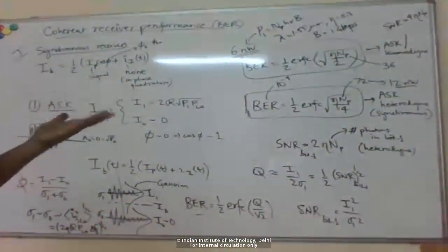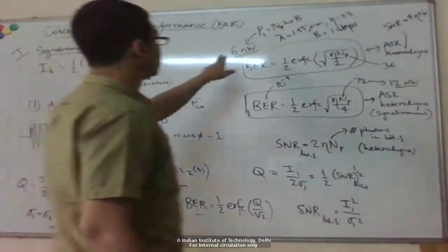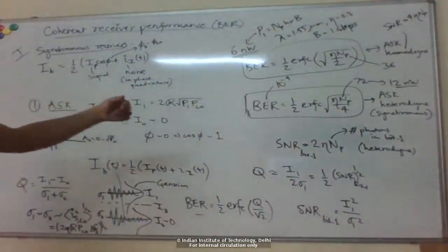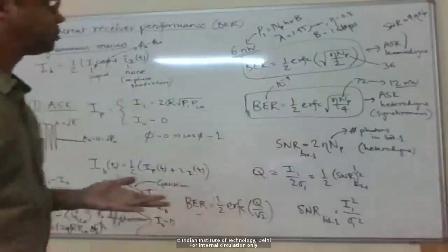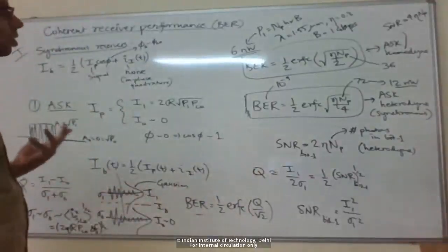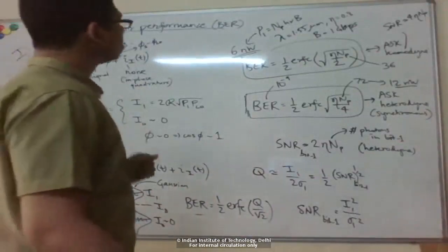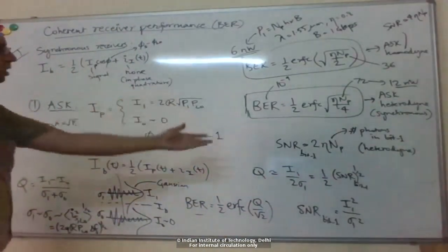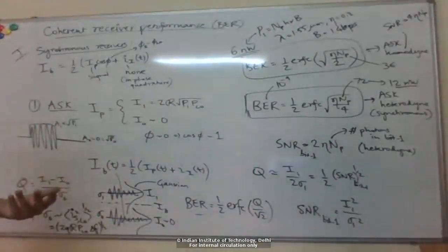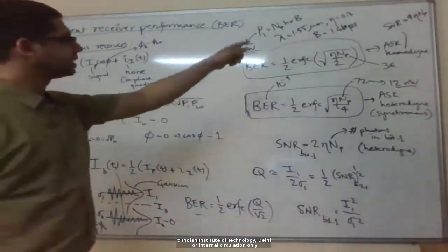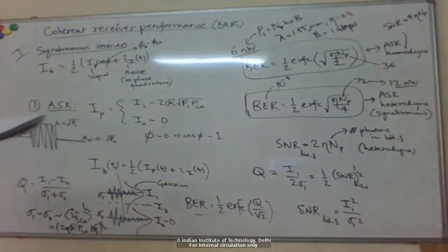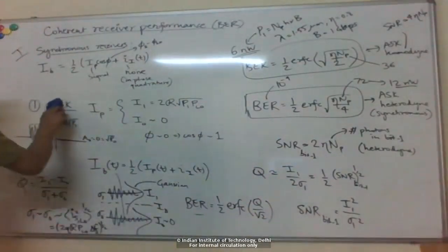Typically we are operating in the microwatts level in the thermal environment with standard detectors, but with coherent detection we can improve the sensitivity by roughly 20 dB, or even more sometimes. This discussion shows you, for ASK or just intensity modulation, how going to coherent detection gives you a sensitivity enhancement compared to direct detection. Now let's discuss other modulation schemes.